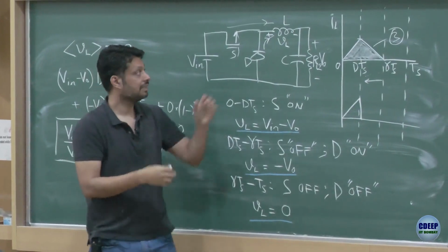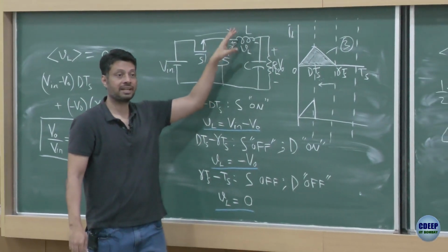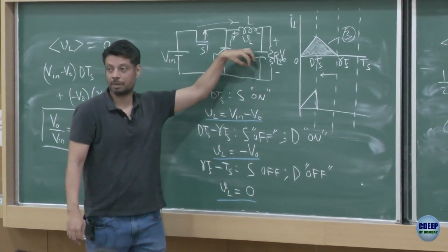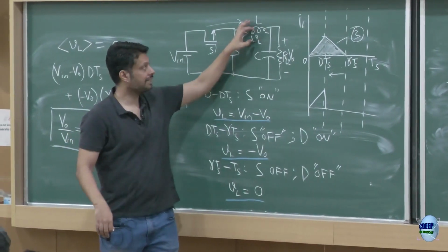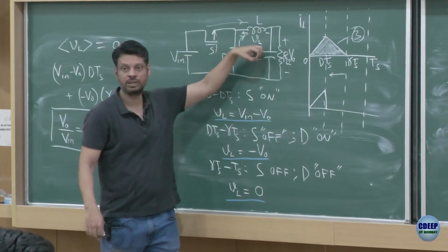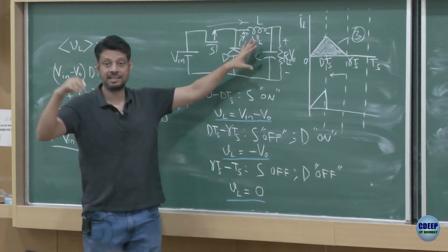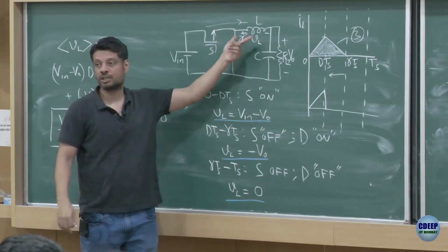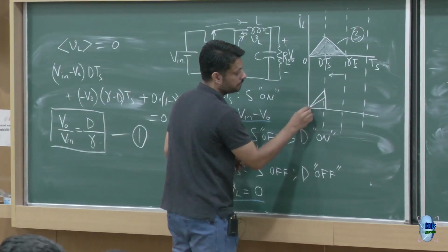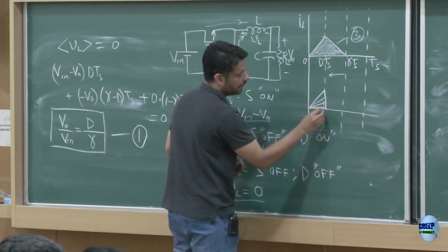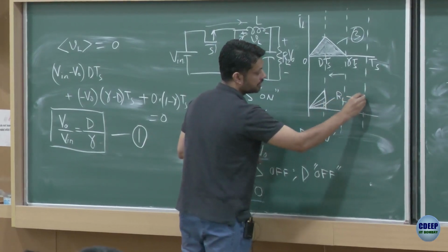So what will happen is, there is an average current here, this average suddenly you have removed. So now this average current will increase the average value of the capacitor for some time, it will be a transient phenomenon, right. So this DC current will flow into the capacitor, and the voltage will keep on rising, right. If this voltage rises, when the switch is on, what happens to the slope? The slope will reduce. So the slope will keep reducing, and practically you would have this kind of condition when RL approaches infinity.